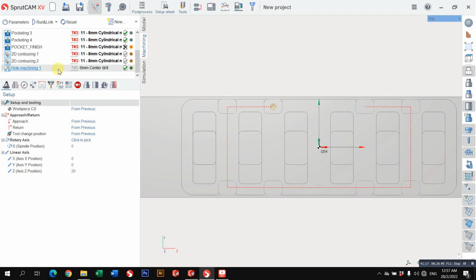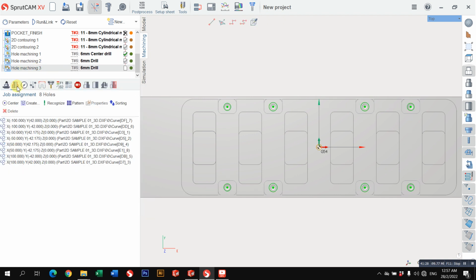Okay. No. I want to do a pocketing based on that, so I will change to cylindrical mill. Okay, using also a 6 mm tool. Now this one we can change this one. Okay, 5.